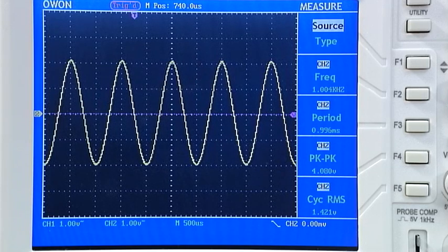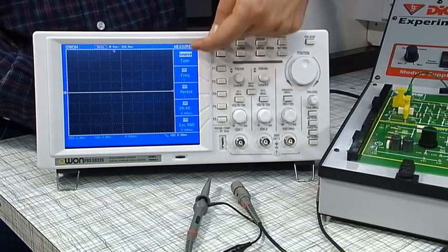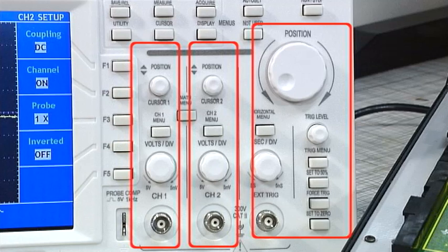The screen of an oscilloscope is used to display the voltage being measured. On the screen is a grid arrangement that can be used to take readings. Time is measured over the horizontal axis, while voltage is measured vertically. The grid is typically 10 by 8 divisions. The quantity that each division represents can be set using the Timebase and Y amplifier controls.